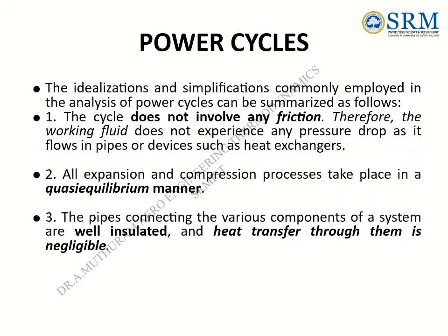The idealizations and simplifications commonly employed in the analysis of power cycles can be summarized as follows. 1. The cycle does not involve any friction. Therefore, the working fluid does not experience any pressure drop as it flows in pipes or devices such as heat exchangers. 2. All expansion and compression processes take place in a quasi-equilibrium manner. 3. The pipes connecting the various components of a system are well insulated, and heat transfer through them is negligible.